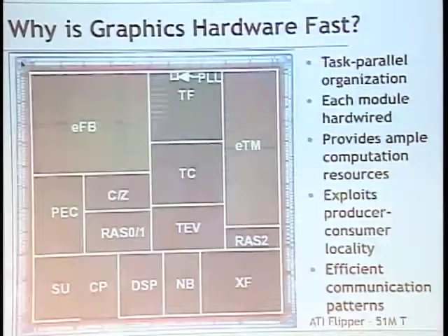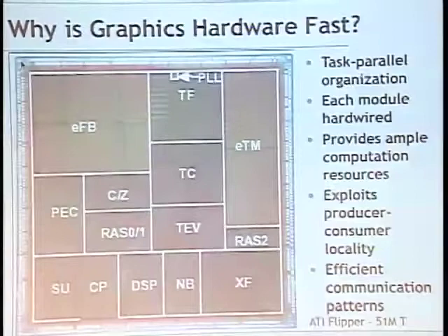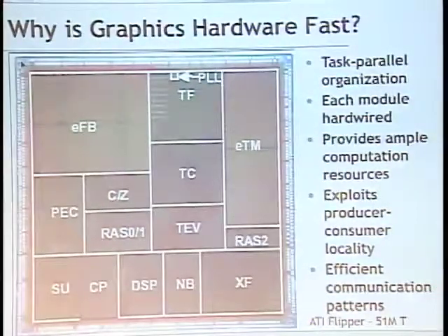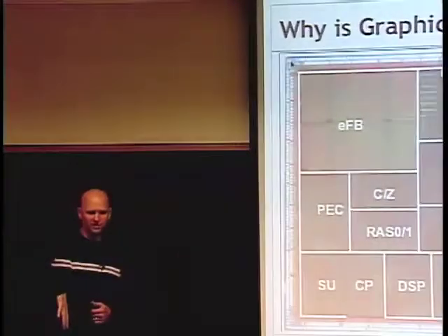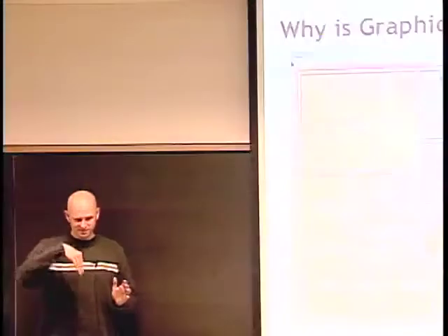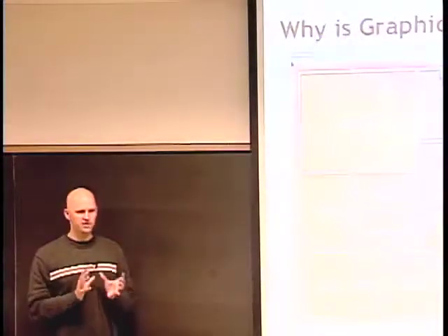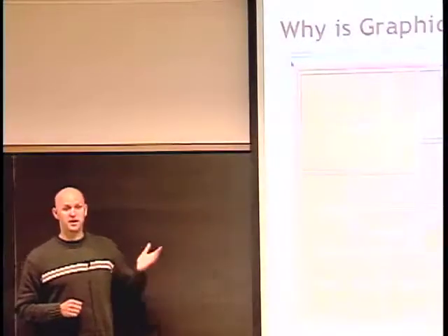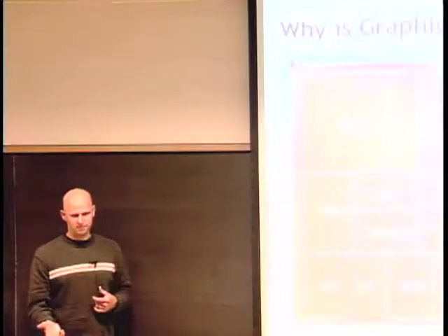Okay, so a big part of the issue is that you have one design flow, one set of technology flow that does CMOS, and a totally different technology flow that does DRAM. So DRAM transistors today are tunneling, and they're sort of turned vertically. It's a trench transistor. So if you look at CMOS kind of stuff, it's basically all on the surface. Okay? To make DRAM really dense, they take the surface things and they basically dig holes in it. I'm not an expert at this in any way, but it's basically a vertical structure that goes down into the chip. So pretty much most structures either do one or the other. Okay? So if you want a hybrid process that does both, that costs more money. So part of it is expense.